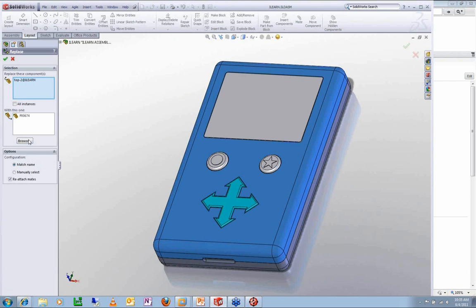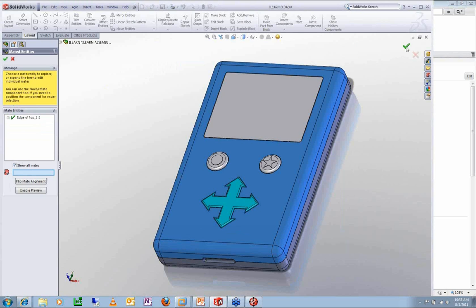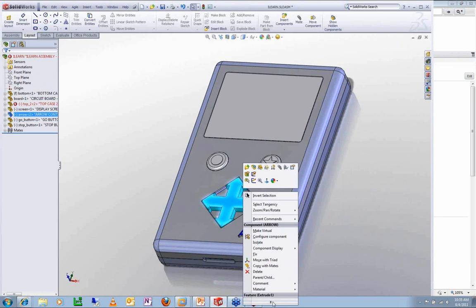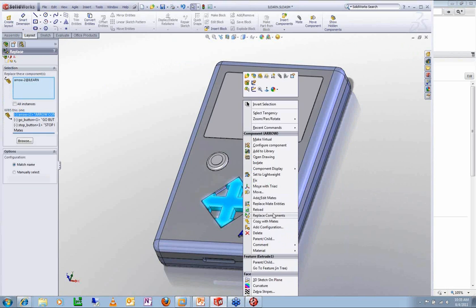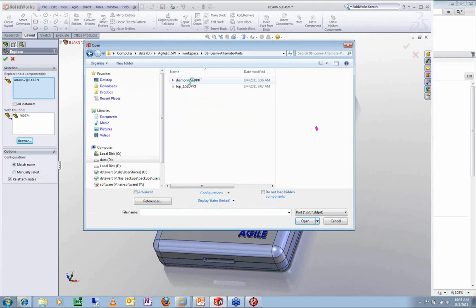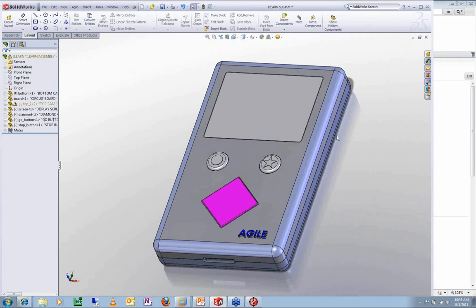So just like you see with the slap chop and vents, through the magic of TV, I'm going to go in here and just pull up a part that I've actually generated before. That way I don't have to actually develop the geometry. Same thing here. I'm just going to do a replace. Replace with this diamond part. So that's the design that I think will work now. Those small facets that I saw with the arrow will no longer catch on the edges and cause it to snap and break. This should be a better design for this little PDA, this little child's device.